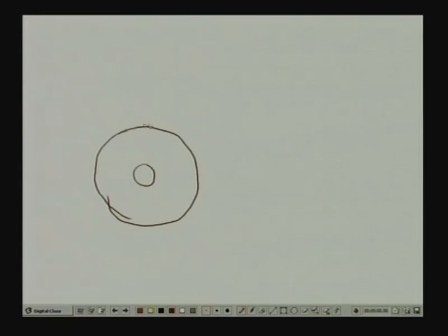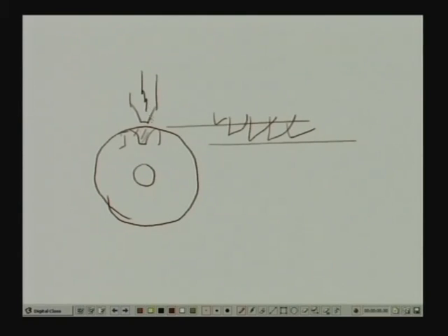Now, actually we do not cut the teeth, we remove a layer of material. This layer of material has to be removed in between two teeth, then next another two teeth have to be produced. How do we do that? We can do that by a shaping tool. Say this is first, and next you gradually increase the infeed. If it is a shaping form tool, then this has to be intermittently moved in radially, like this.